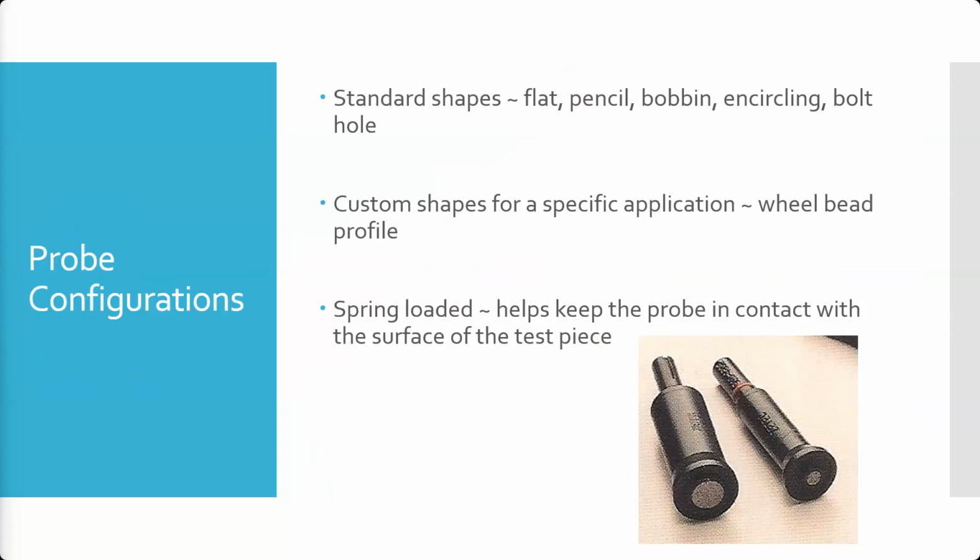If I just take a probe, like if I have this probe and I wobble it a little bit, I'm going to get an indication. I cannot hold this steady enough to not get some kind of little indication. This one's pretty good. It's got this nice flange. You can hold it nice and tight. Spring holds it against it, but it'll still get a little bit of movement as you move it across the part just from surface roughness.